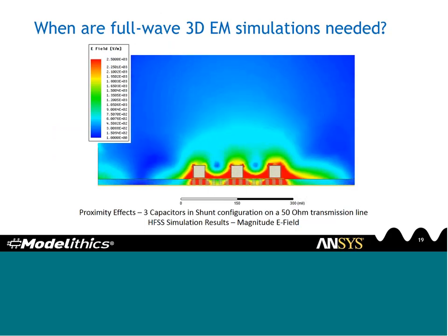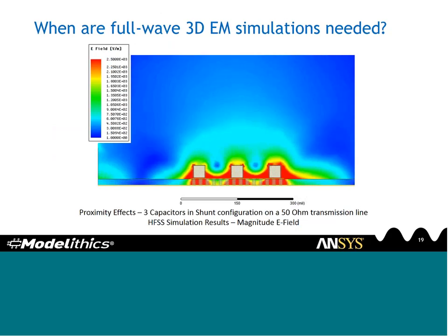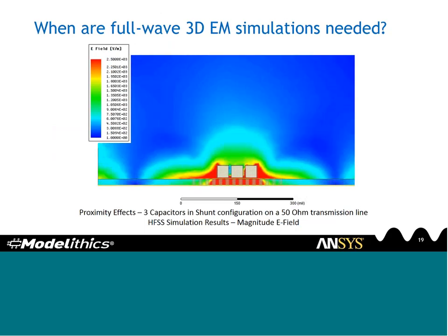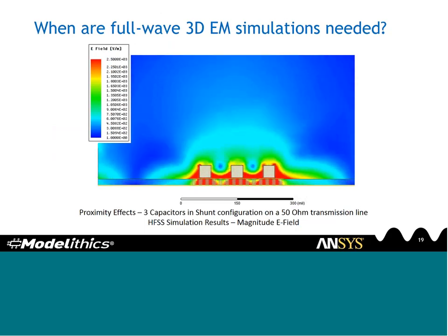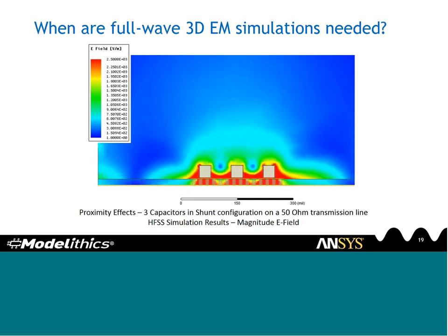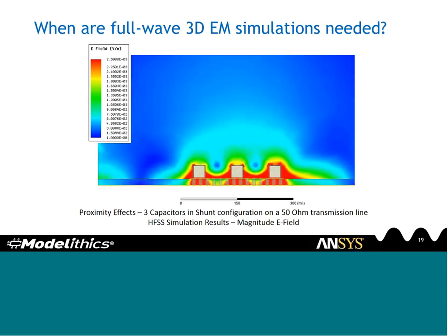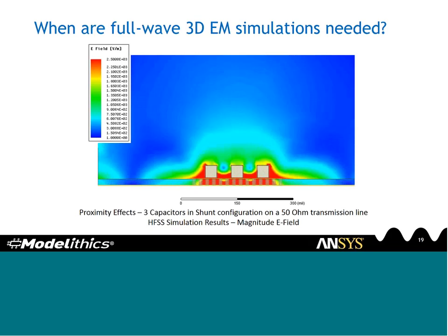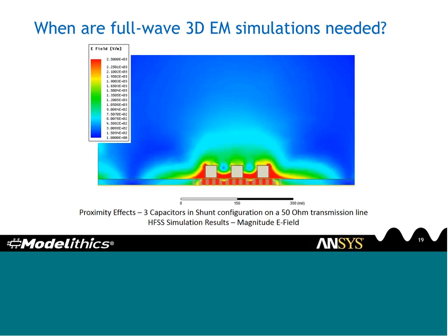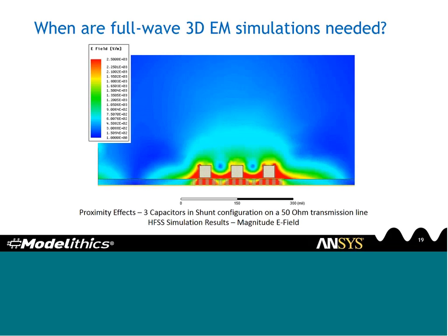So, when would a 3D EM simulation actually be needed? As previously mentioned, the weakness of equivalent circuit models is that they're developed in isolation. So generally, you can't account for any of the component-to-component coupling or component-to-surrounding-environment coupling. When all of the components in your design are spread out and separated by sufficient distance, or the design is relatively low in frequency, this won't generally affect your results. Circuit simulation of components and planar EM simulation of the traces will typically be enough for designers. However, compact topologies, higher design frequencies, and increasing product complexity can mean more electromagnetic interactions between closely spaced microwave components.